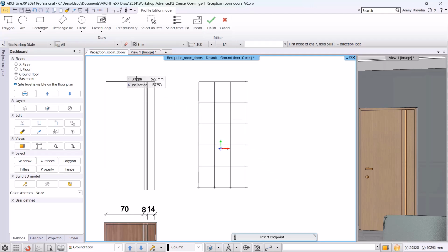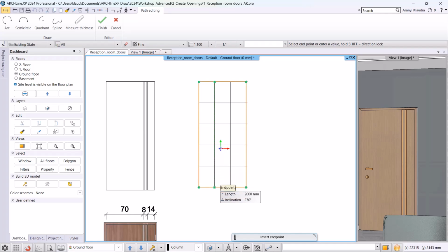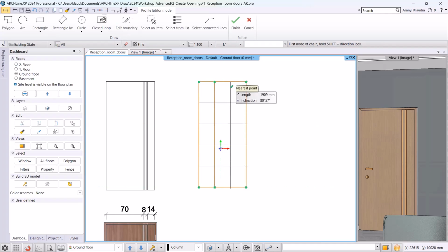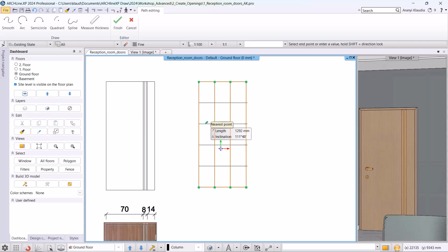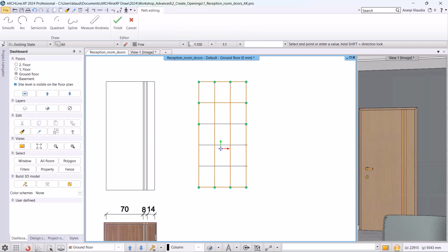The program helps us how to prepare it. We have already created a closed or even an open profile, but not yet one with a closed profile and several open profiles. So that's what we are going to look at now. First, I will create a contour with a rectangle, so the closed profile into which I will create open profiles. So I will draw these vertical and horizontal lines.